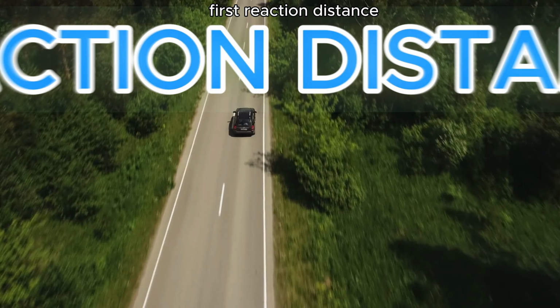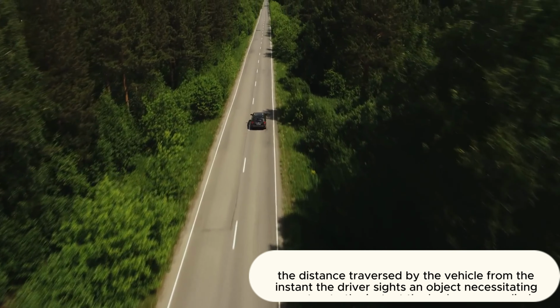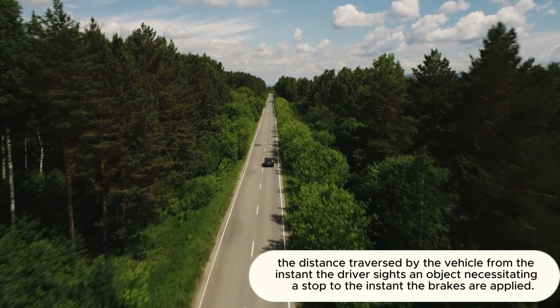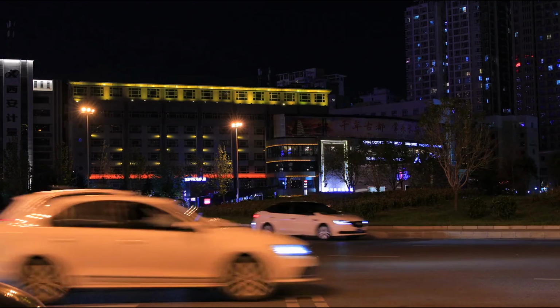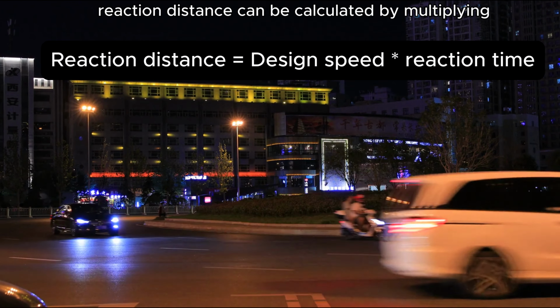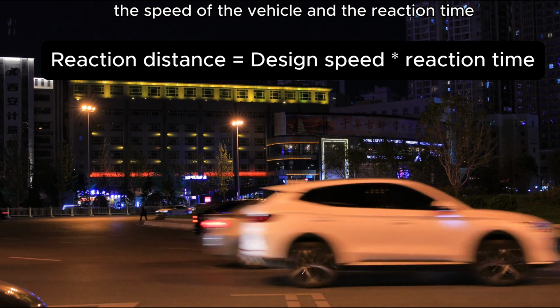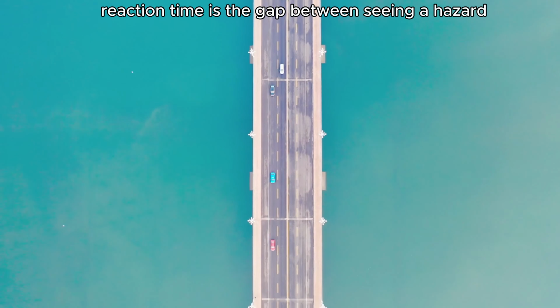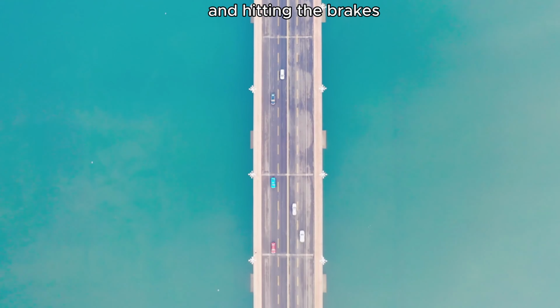First, reaction distance. The distance traversed by the vehicle from the instant the driver sights an object necessitating a stop to the instant the brakes are applied. Reaction distance can be calculated by multiplying the speed of the vehicle and the reaction time. Reaction time is the gap between seeing a hazard and hitting the brakes.